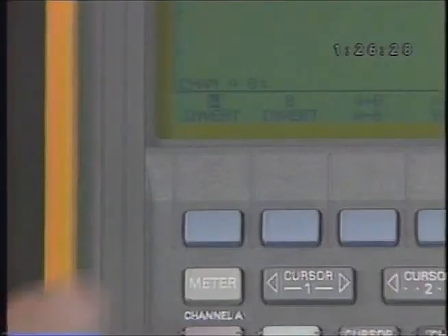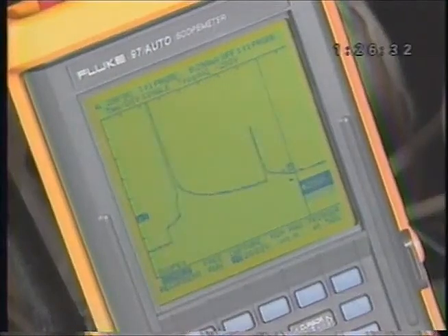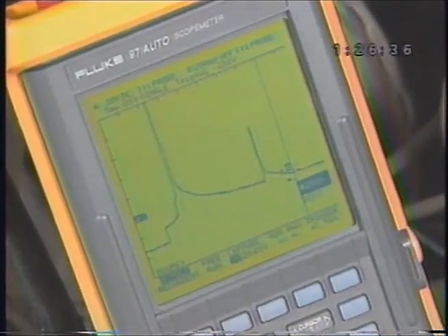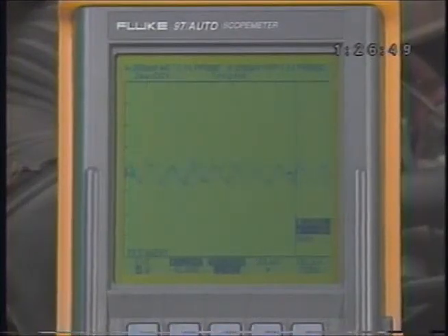There's another feature of Scopemeter you could use to look for these spikes, A-invert. A-invert effectively flips the display. The voltage level and slope are still negative, but now negative is up. The setup for this exercise will be useful in the shop for diagnostic procedures. Save it to Setup Memory 8. Now let's look at a more consistent electrical noise developed by electric motors.